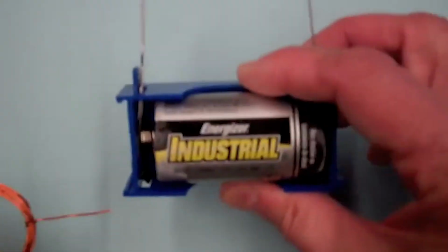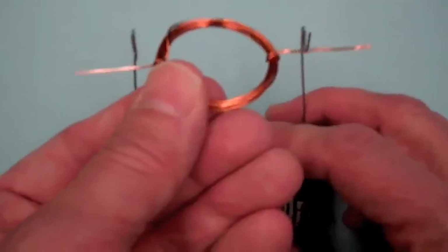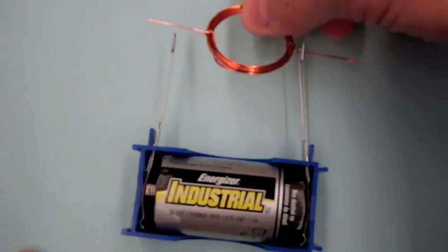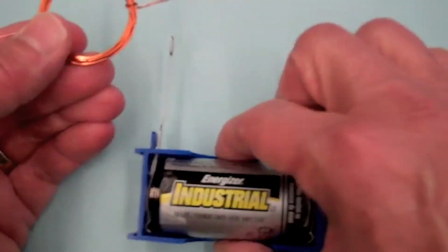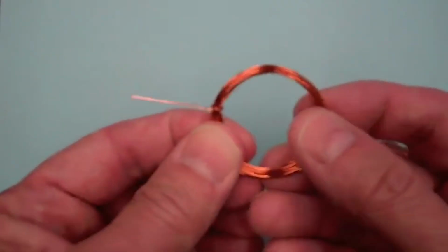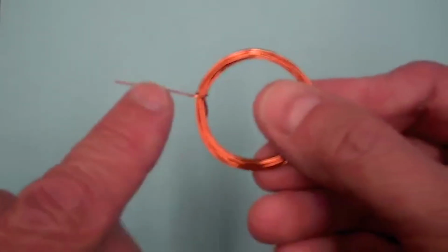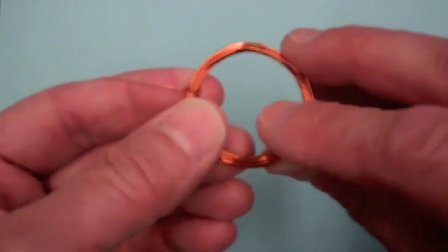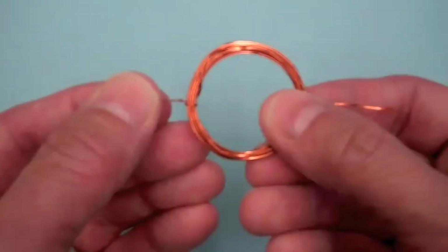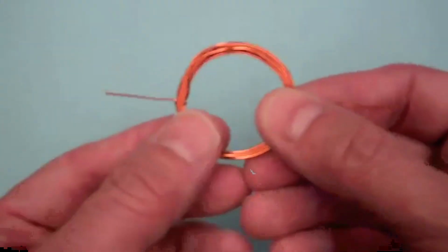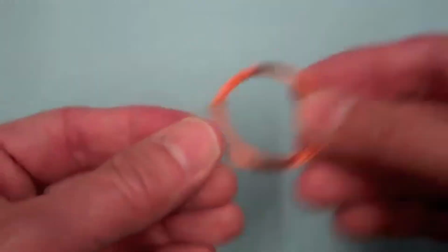Now what I have here is a battery with just a couple of paper clips so that I can pass a current through this loop by laying it against these paper clips. Now I don't actually get commutation. What I've done is I've just removed the insulation on one side of the wire here, so that when it rotates and the magnetic dipole moments align, the current stops because now the insulation is touching the paper clip, and momentum will carry the loop around.